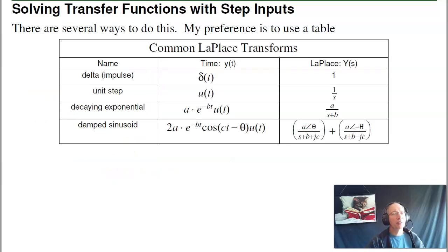That's what you covered back in circuits 1, circuits 2. In signals, you cover Laplace transforms. Now there's tables upon tables upon tables of Laplace transforms. I found you really only need 4. The Laplace transform of a delta function is 1. We'll just take that as an assumption, go back to signals to see that derivation.